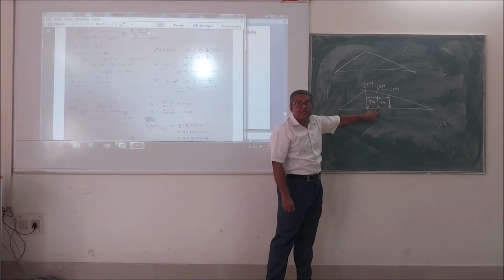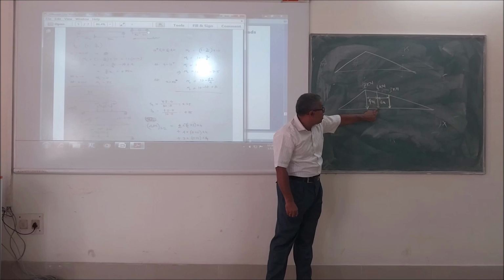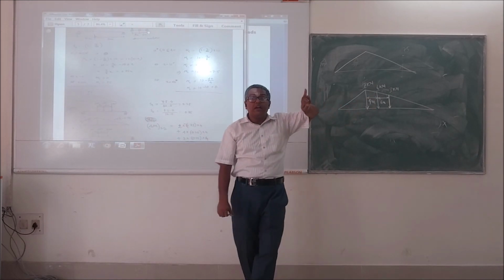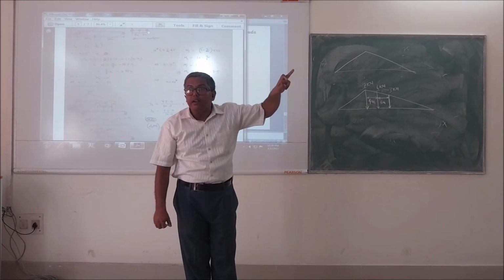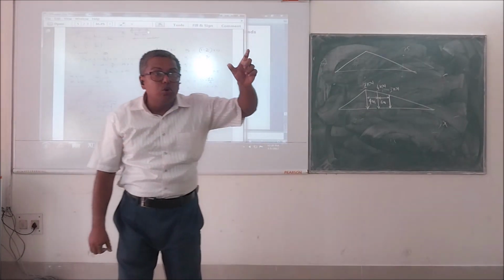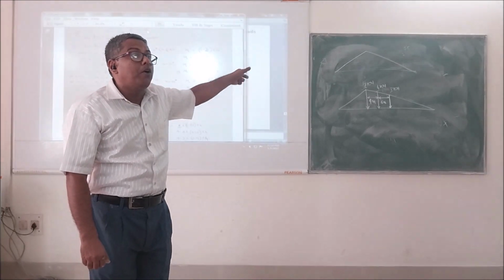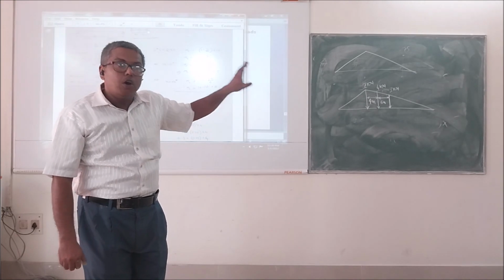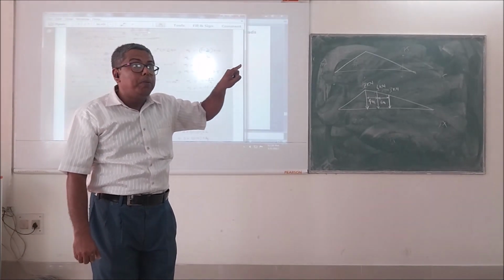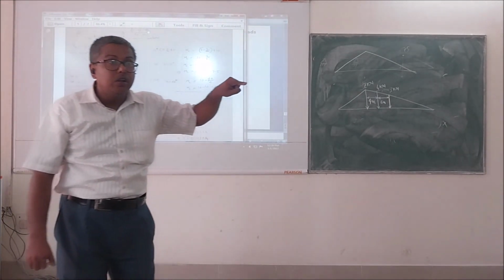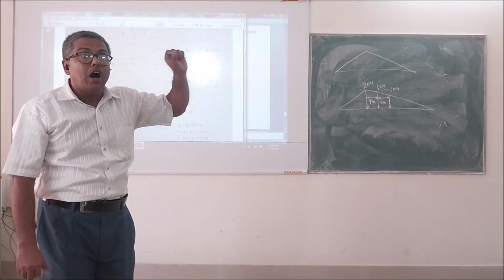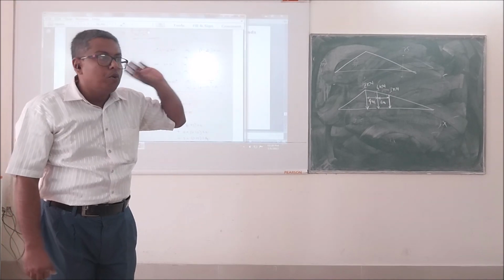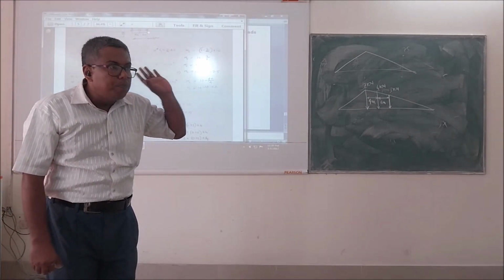Please clearly understand this. This is very important. I am telling you, if I want to bring, what will be my critical position? Next critical position will be what? My next load should be placed on the maximum ordinate position. So what is the next load behind 2 kilonewton? 4 kilonewton. So if I want to place the 4 kilonewton load on the maximum ordinate, how much should I move? I should move by 4 meter.